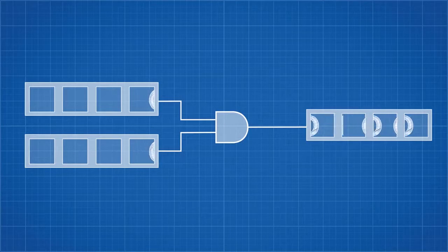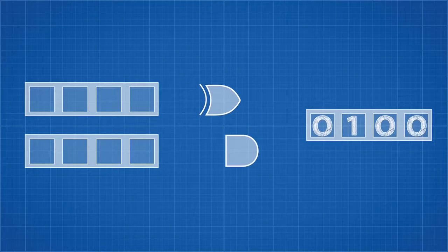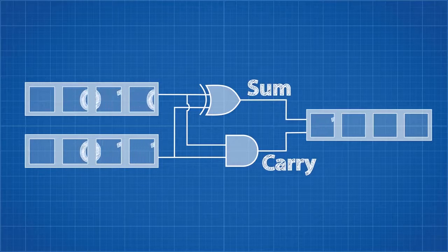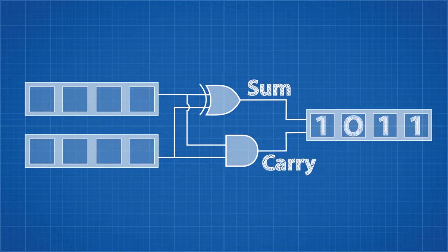If we wire these logic gates like this, we create a half adder, which gives 2 outputs, our sum and our carry. This allows us to add our binary number 1 bit at a time. A more complicated circuit is needed to perform the calculation in one step. Modern computers can perform millions of these calculations per second, and they're still getting faster.